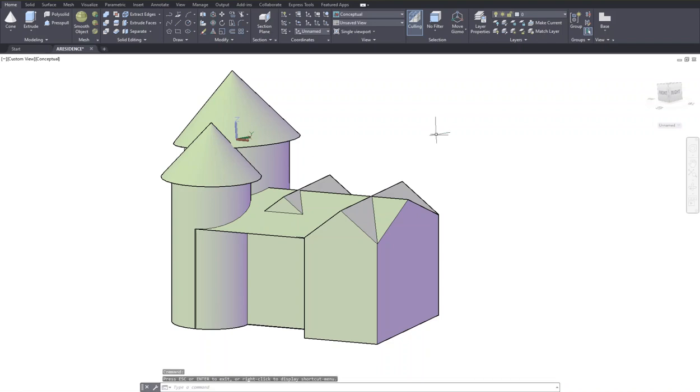Okay, so hit escape and click save again, and we do that as often as every time you accomplish everything. And what is missing here in general? Windows and doors, and then trim. Trim is what we call the part of the wood parts sticking out of the roof about 2 inches or so. That's very important. And we need stoop, that's a concrete, about say 9 inches high concrete step in front of the exterior door.